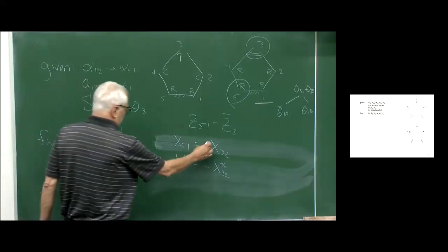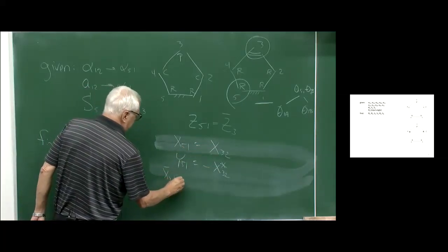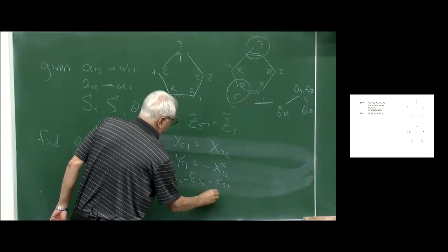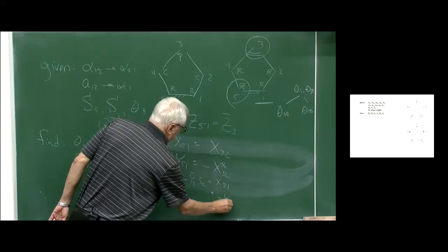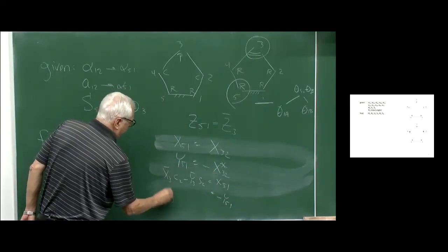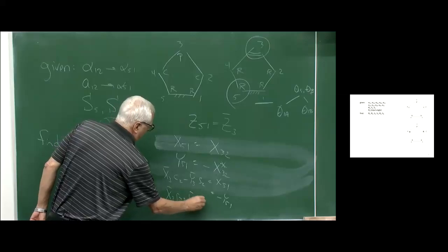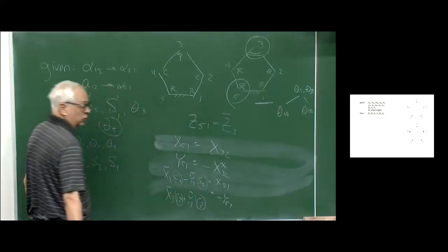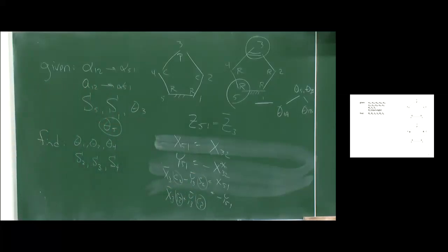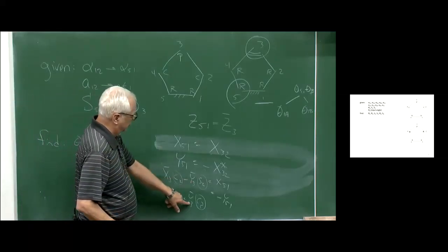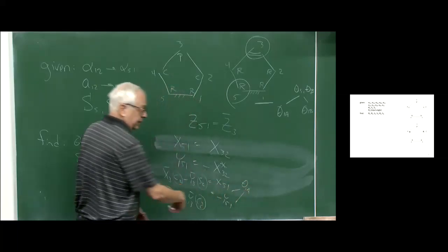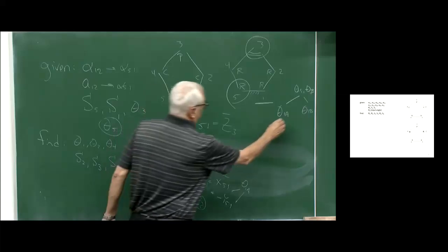We're going to expand the definitions of x32, xc2 minus y3 bar s2 equals x51. I'm going to move that minus sign to the other side and expand that, xs plus yc. And again, here's our unknowns. So we got 2 linear equations and 2 unknowns, just like the previous chapter. We're going to take the given theta 3, turn those into numbers, the given theta 5, and theta 1a. So for the A case, I have 2 equations, 2 unknowns. I'll solve for the sine and cosine of theta 2.